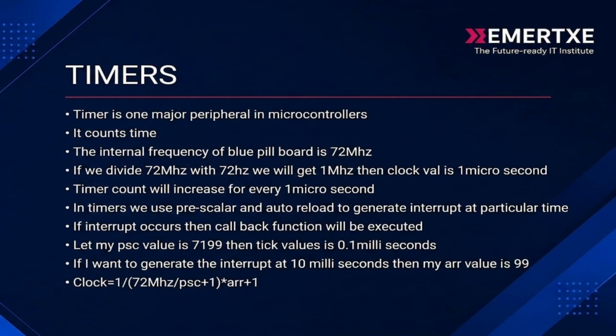Timers. Timer is one major peripheral in microcontrollers. It counts time. The internal frequency of the Blue Pill board is 72 megahertz. If we divide 72 megahertz by 72, we will get 1 megahertz. Then the clock period is 1 microsecond. The timer count increases for every 1 microsecond.